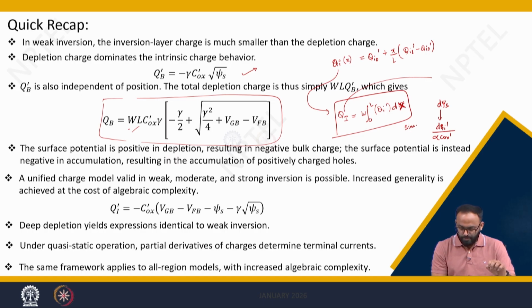We said that when you change VGS, the region of operation changes from accumulation to depletion to weak inversion to moderate inversion to strong inversion. First you will face saturation, and then you will go to non-saturation because you are changing VGS, and you should take care of the limit of the saturation and non-saturation boundary, which is defined by (VGS minus VT) divided by alpha.